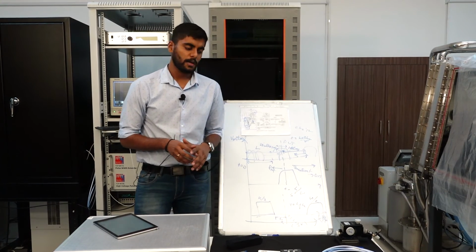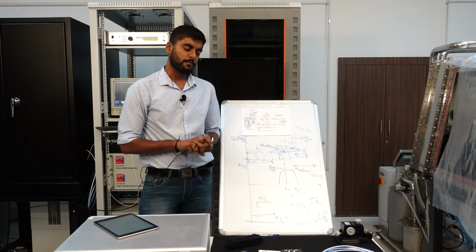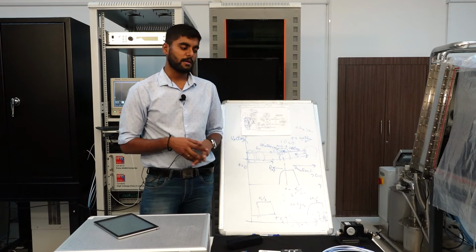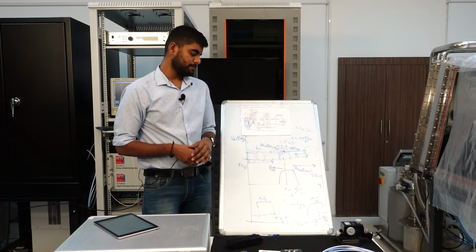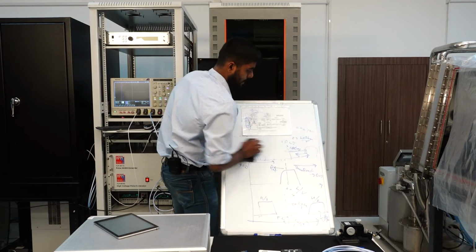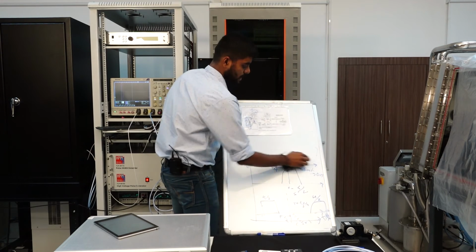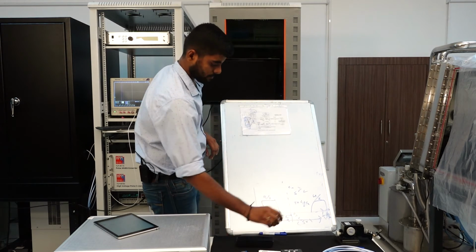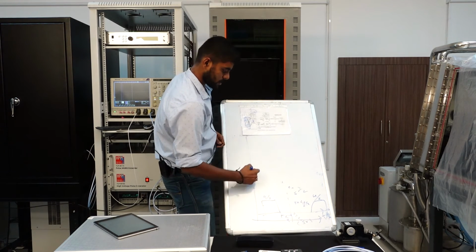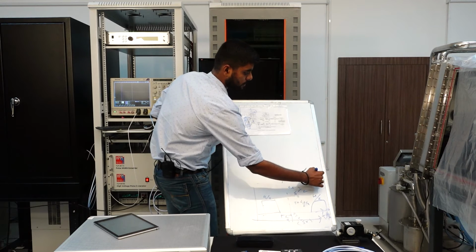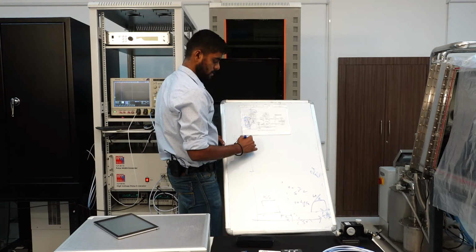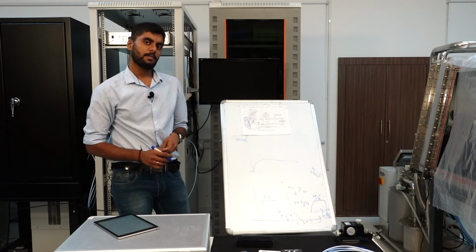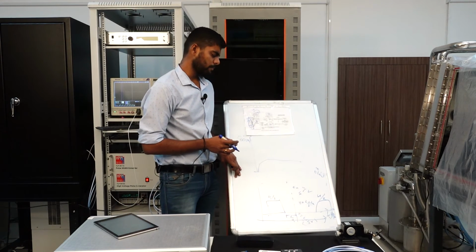Now a couple of things to take care of. When I was talking about your TLP setup, if you remember, in the very start I was talking about these different models: HBM, CDM, MM as well. An important thing to know here is that all these different models also have different waveforms, which are somewhat different from the TLP generator. So again, this is time versus current. Your HBM has a waveform somewhere like this, a decaying waveform, roughly rectangular in shape, but decaying.